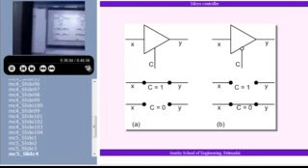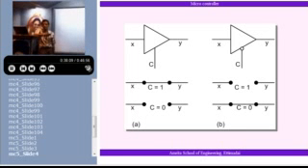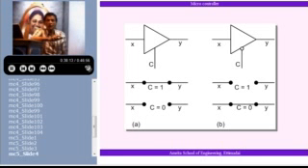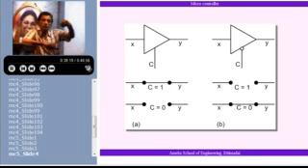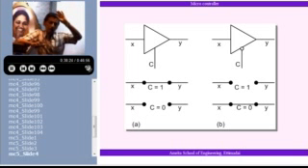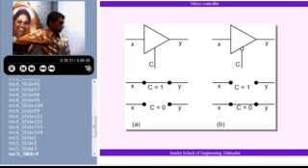It is called tri-stated. So far, we were talking of digital variables where they will take value 0 or 1, high or low, only 2 states. Here, I want to introduce a new state. The output line is simply left floating. I don't commit. I tell the output line, I have no connection with you, you are left to yourself. It is left floating. It is called a tri-stated output. Here it is connected directly, here it is not defined. Hence it is called a tri-stated state.